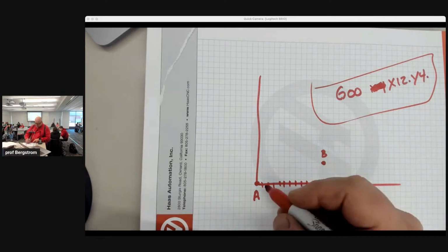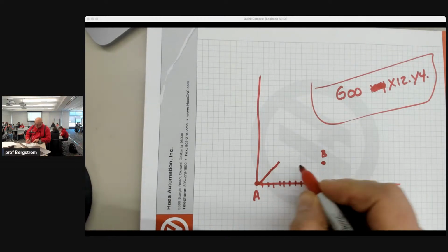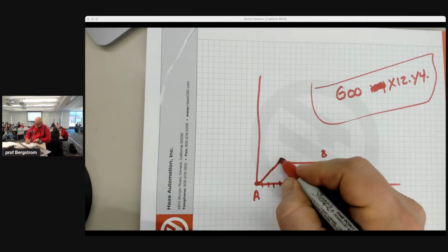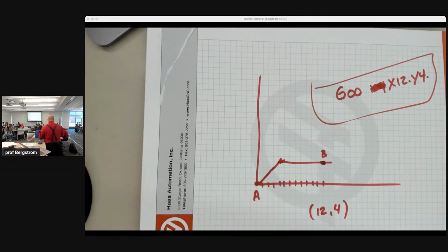And the motion that it would take would be this and then this with some slight overshoot there and some slight overshoot there. So the way it's going to do that, it's going to start the X servo motor as fast as it can spin and start the Y servo motor as fast as it can spin. I'm assuming they both have the same maximum speed. And I'm assuming they both have the same gear ratio. So it's going to spin them both the same as fast as they can go.